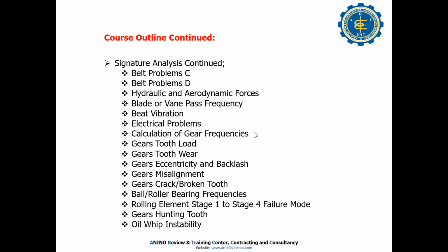When I see this, I am happy because 100% I can tell our management that the problem is the blade pass frequency. But if the problem is 1x, there are many possible problems, so you have to check all the components of the rotating machines. It's not like with the blade pass frequency, where the peak is already there.